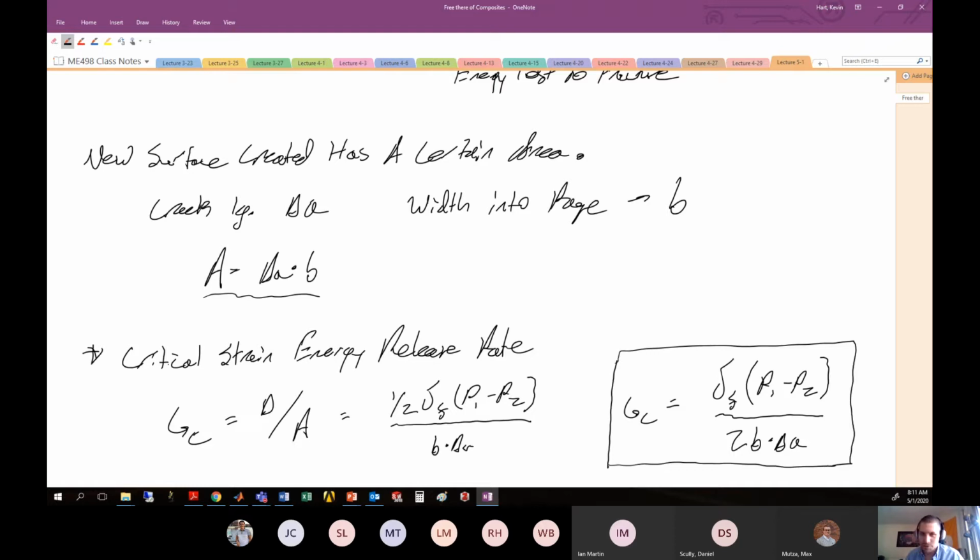Now, if you're doing an experiment, usually you don't want to just go with like one value. Okay, so you don't want to just run one test. Usually it would be more useful to have multiple tests. Okay, so what people do in real life, if they know they have a brittle material, is they'll load it, load it, load it, and then they'll see a reduction in load and constantly track the crack at the same time.